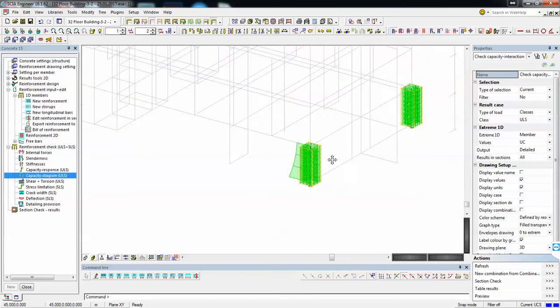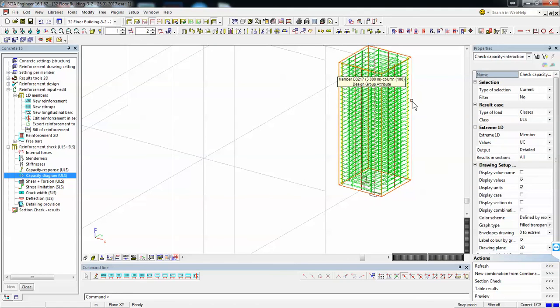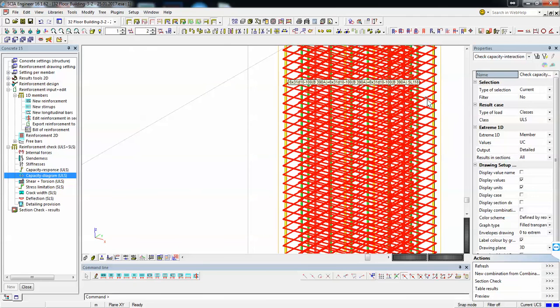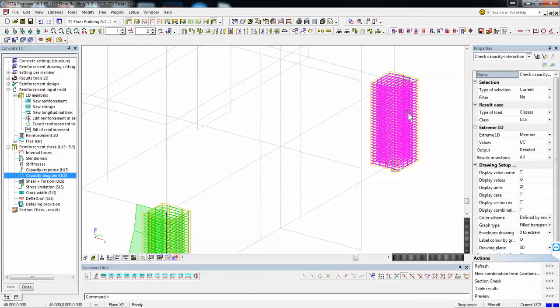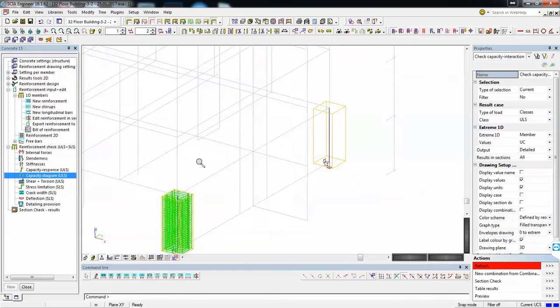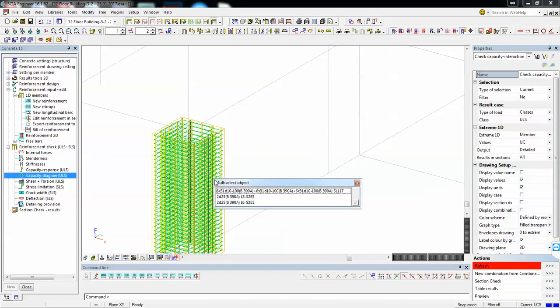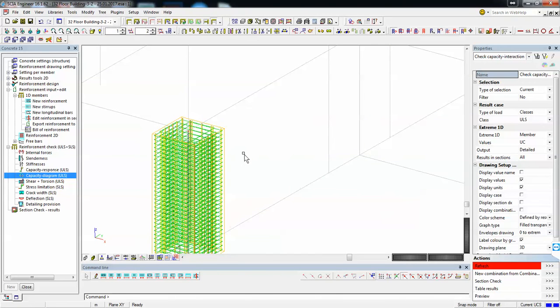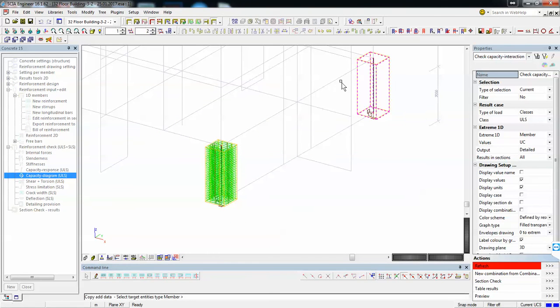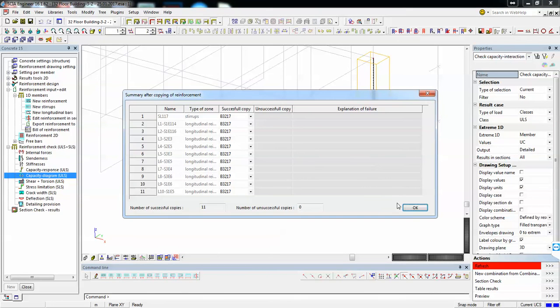So this is how we handle the problems. But you have to do the other reinforcements. I gave you a few examples, and now you'll have to go and follow upwards the structure, change the reinforcements. It's better to start with many bars and then start reducing them once you go on top.